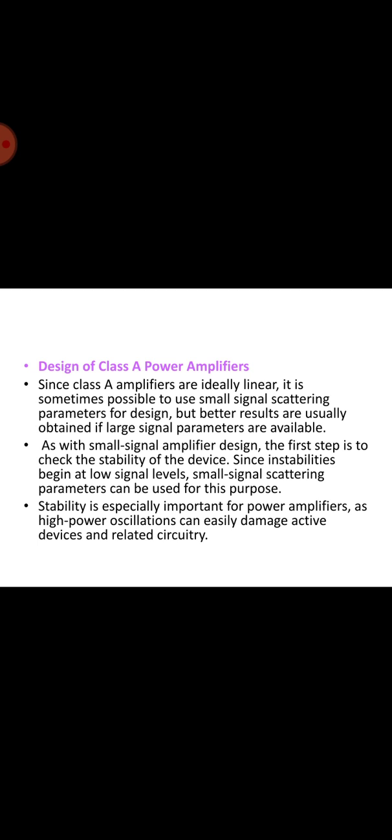These are called load pull contours, and they are obtained using an automated measurement setup with computer controlled electromechanical step tuners. Load pull contours are similar in function to constant gain contours, but they are not perfect circles due to the nonlinearities of the device.